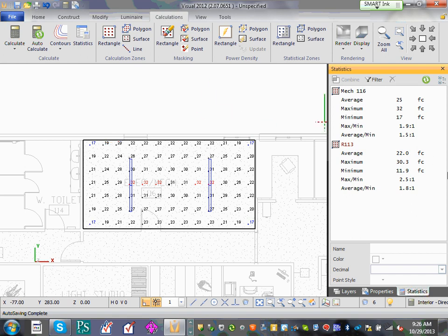Are you guys aware that the red numbers are the brightest foot candle in the middle here? They're always red, and the darkest spot will be the corners in blue. Can you see that? That's your minimum, and that's how this is actually calculated. That's a maximum minimum ratio.